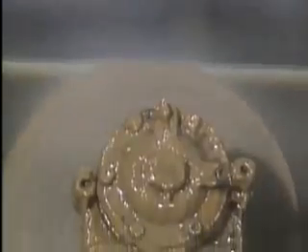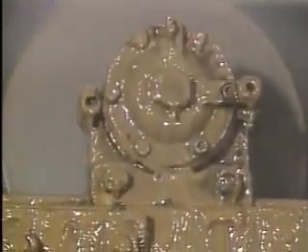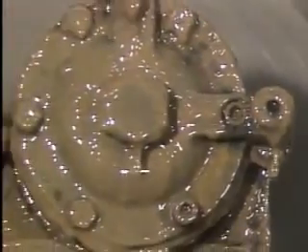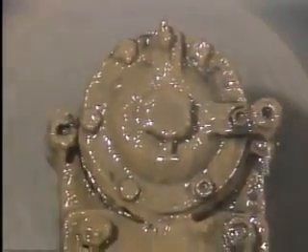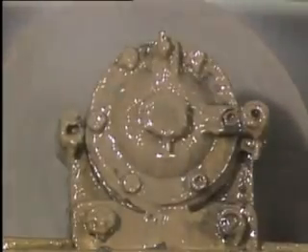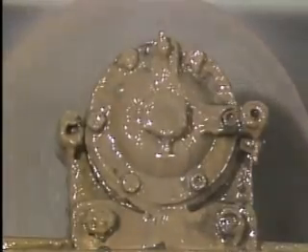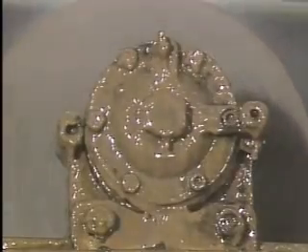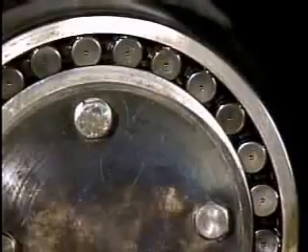This bearing housing is constantly exposed to hot water vapor. Water works its way into the bearing and contaminates the grease. To keep the water from collecting in pockets in the grease and corroding the bearing, a water-stabilized grease is used. Although water and oil or grease normally don't mix well, an additive in the grease used in this bearing makes the water and grease mix thoroughly.